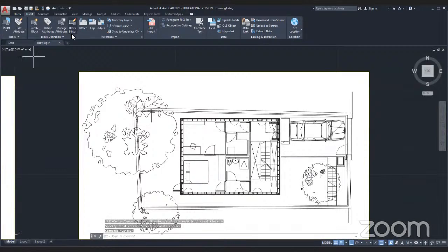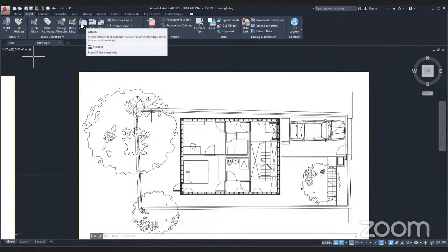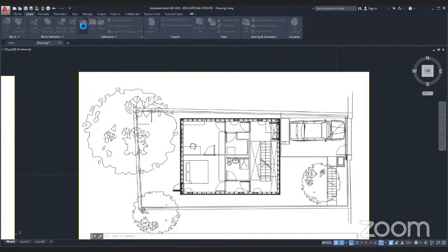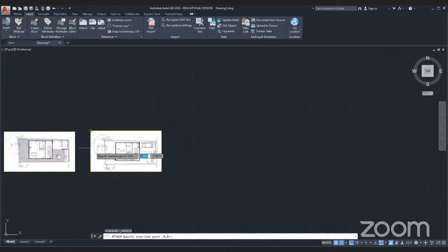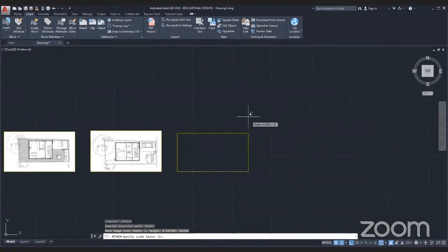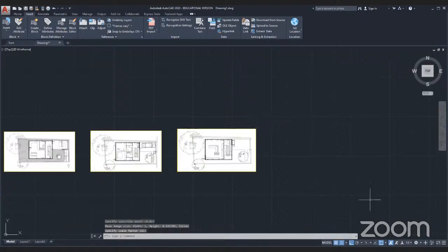Okay. All right, so I'm going to continue bringing in drawings to see if there's any information on these drawings that will allow me to scale our documentation. 12, 13, 14. Hit OK. Insertion point. Keep in mind, I still have my ortho settings on so that everything comes in straight. If I turn my ortho settings off, then things can come in lopsided, skewed off to one end.